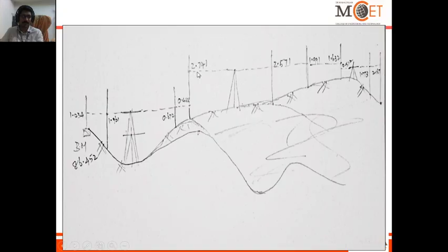Readings were taken until the change at the seventh station: fourth, fifth, sixth, seventh, until the instrument is shifted. So this becomes the foresight, and the remaining ones become intermediate sights. Then the instrument was shifted again, the backsight was seen over the same point, then intermediate sights, and the last station. This is how the flow goes, right? Try to draw and imagine it also.